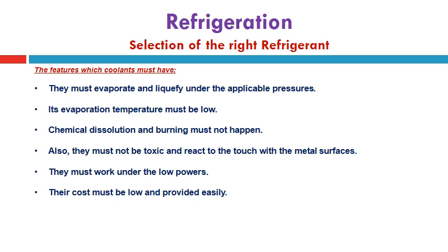Finally, the features which coolants, or our refrigerants, must have are the basis on which our selection must be performed carefully to select the right refrigerant according to the heat pump or the refrigeration machine under consideration. During the design stage, we must consider the following features as listed in this slide. They must evaporate and liquefy under applicable pressures.